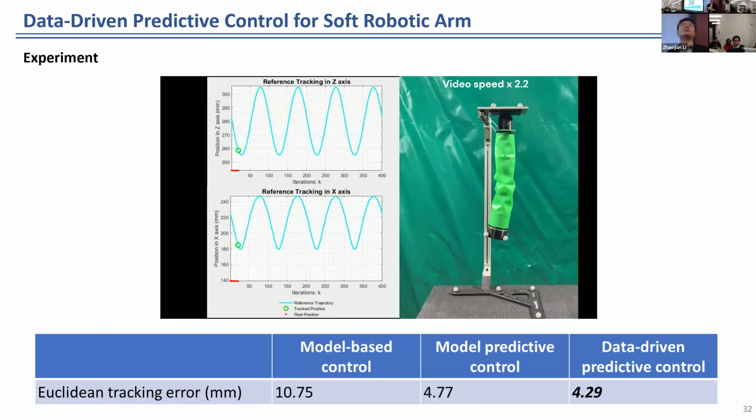Yeah, I mean, all those things are really good directions to explore. And we tried some of those things. Basically, you have a collaboration between two arms. One arm moves the branch to the side so that the other arm can approach the fruit better. We did some study on that. It's doable, but practically probably not a good way to go. If you cannot pick the fruit, just pass. And we want to engage with the growers next season, do better pruning, so that there are no branches sticking out. That's a better way to address the problem instead of making the system too complicated.